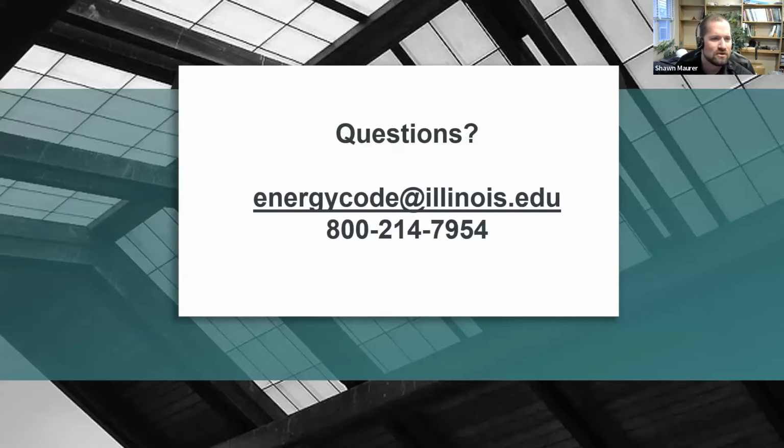So that brings us to our last poll question. Where are automatic receptacle controls required? Hotel rooms, classrooms, commercial kitchens, enclosed offices, convention centers. There are multiple correct answers here, so pick the ones you believe are correct. And what loads are required to be monitored? Again, multiple correct answers. Receptacles, total building, electric vehicle chargers, and facade lighting.